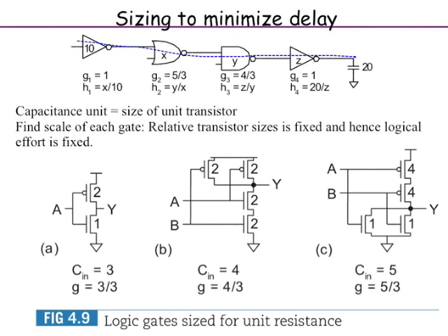So it is the same as the capacitance, because I had to just multiply with some proportionality constant. So it's really the capacitance. Input capacitance is 10 times some k femtofarads. K is a constant, but we'll just call it 10 because we are just doing relative sizing with respect to this input. 20 is also expressed in terms of the gate sizes, just to keep everything in the same units, so that calculations become easy.